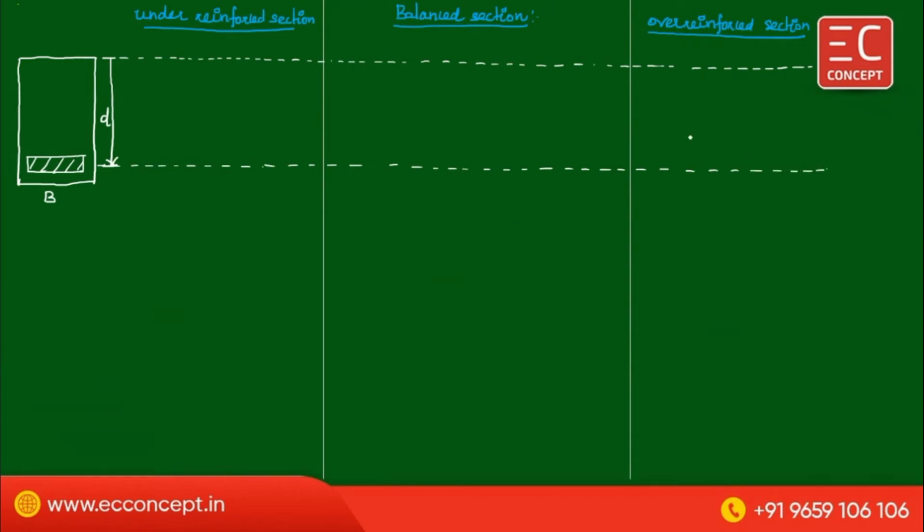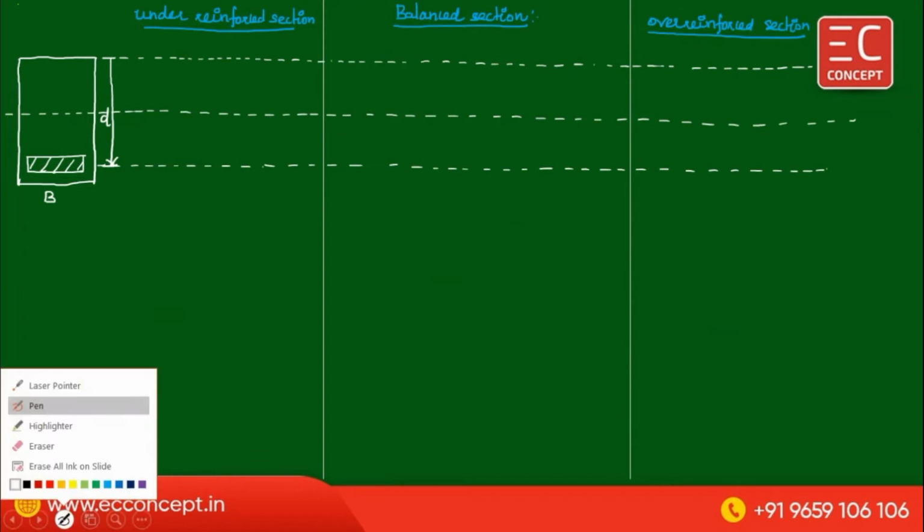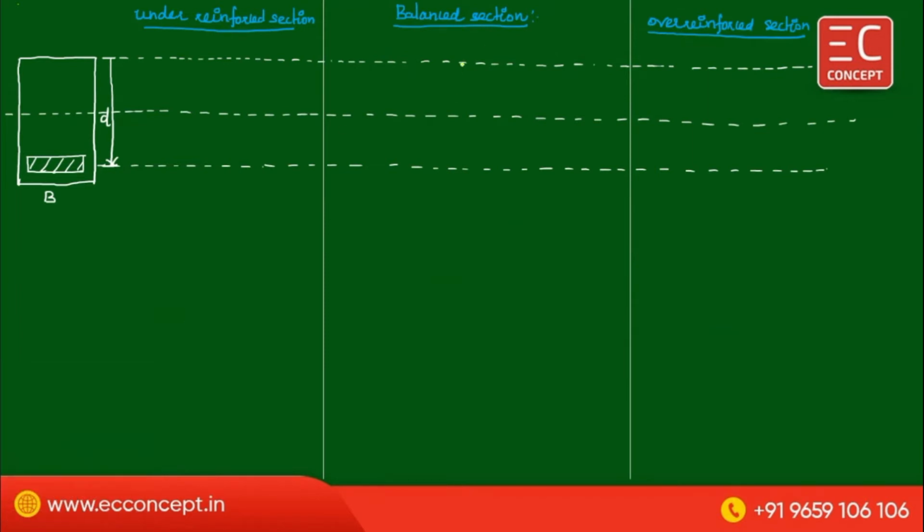Now the analysis for the balanced section. In the balanced section, the concept is that the steel and concrete attain their stress at the same time, simultaneously. So the neutral axis goes somewhere here. This is the neutral axis, and this is the stress block.